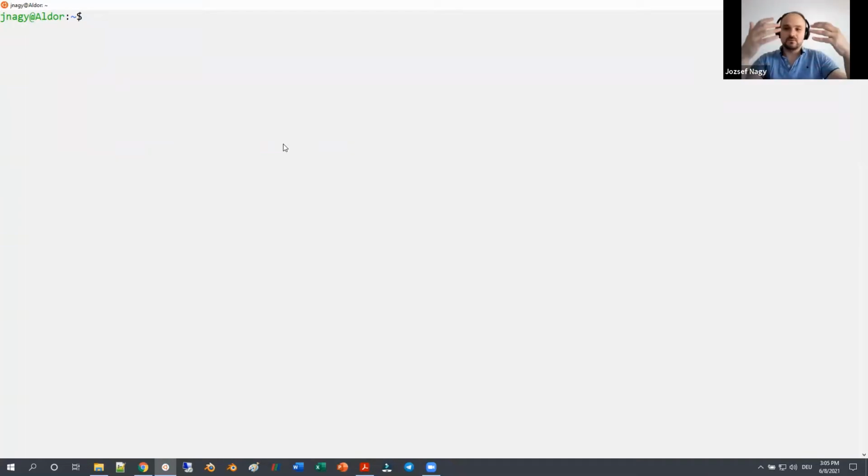It is important that if you have OpenFOAM installed, you use the correct version. Either this is done automatically for you once you open up the terminal, or you have to type in source and then the path to your OpenFOAM installation, in etc and bashrc. This is how you load your OpenFOAM installation. You can also shorten it, but this is the command that you need to load 2012.